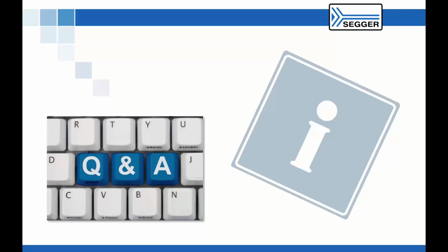One question was, what is the ideal J-Link probe you recommend to get full advantage? I think I mentioned that you can use SystemView with a lower end probe, but the higher end J-Links with the higher target interface speed will give you better performance, and you can do more events.